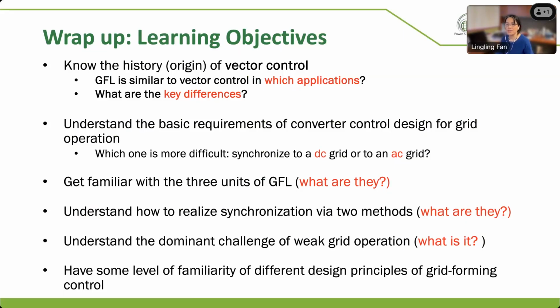The differences, in fact, we just talk about torque and flux become like real power and reactive power. Additionally, there's a synchronized unit. In motor drive control, you do standalone. Here you have a grid, right? So there's a synchronized unit. That is related to how you generate the angles. And in motor drives, I think how you generate the angle is also a big challenge. In grid, this is using PLL and power. And that's the technique that we use.